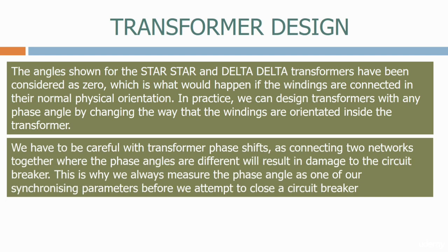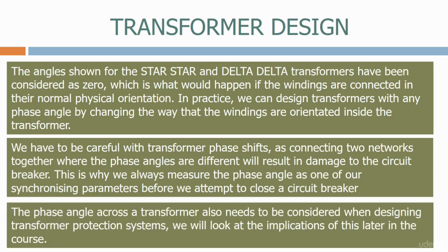We have to be careful with transformer phase shifts, as connecting two networks together where the phase angles are different will result in damage to the circuit breaker. This is why we always measure the phase angle as one of our synchronizing parameters before we attempt to close a circuit breaker. The phase angle across a transformer also needs to be considered when designing transformer protection systems. We will look at the implications of this later in the course.